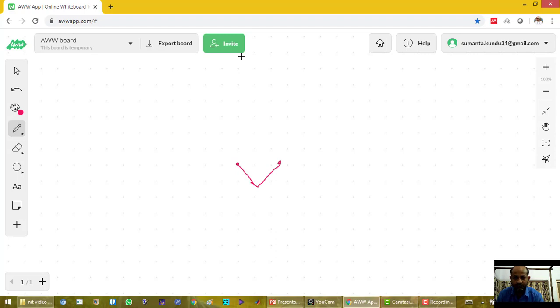Okay, so this is my two fields, one rotating clockwise, one rotating anti-clockwise, A and B. So the resultant is this, right? The resultant is this for position 1. Now again if we take a different position 2, again we will get the resultant in this direction with a lesser value.